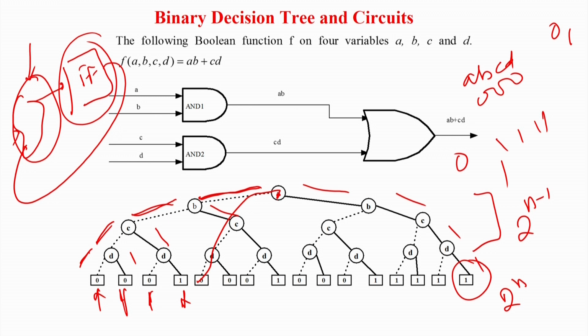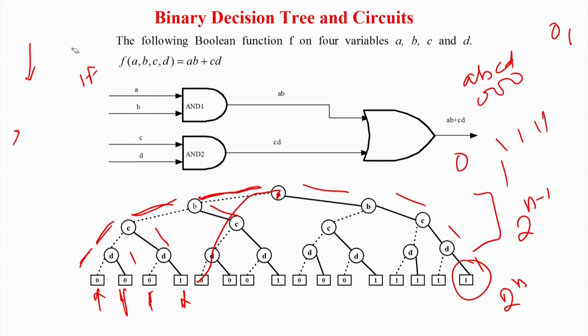That modeling is not difficult if we can have a good data structure to model the NSF block, that is the next state functional block, which is a combinational circuit. That is why we are mainly dealing with combinational circuits here when we are explaining binary decision diagrams. For the time being, we just assume that if I can model the combinational circuit in a very nice and efficient manner, we can handle the complexity there, then modeling of the flip flops will be trivial, right.